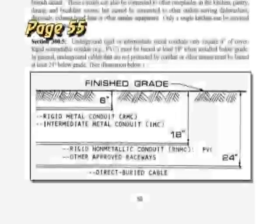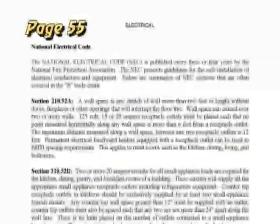Now, staying on this same page in which that illustration about finish grade is, but going to the top of the page, we're talking about the National Electric Code. It has certain demands. Let's look at one of the demands, and that is in section 210.52a toward the top of the page. That's underlined 6 feet. That's underlined 12 feet. Those are some basic units of measurement that indicate exactly where outlets are to go and how frequent they are to go in a room. Read through that. That will help you understand how frequent you have to put in an outlet.